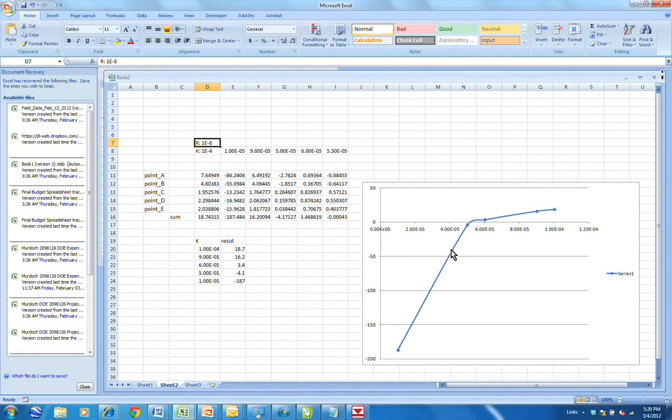So hopefully if you plot the data as you go, it gives you some structure so you're not just flailing around trying many different combinations. This is the manual procedure for calibrating groundwater models, and you should be able to calibrate this one with, you see it took us maybe 6 tries here. We started with one and then we had 5 tries, and maybe one of these was really close enough.